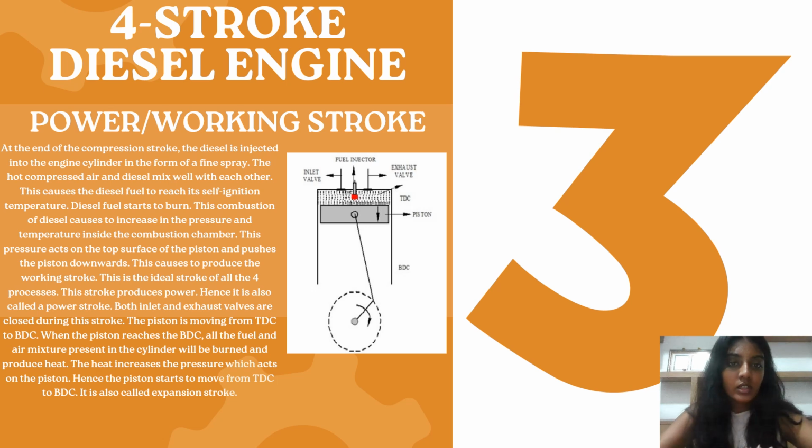Next, we have the power or working stroke. At the end of the compression stroke, the diesel is injected into the engine cylinder in the form of a fine spray. The hot compressed air and diesel mix well with each other. This causes the diesel fuel to reach its self-ignition temperature. The diesel fuel starts to burn, and the combustion of diesel leads to the increase in the pressure and temperature inside the combustion chamber. This pressure acts on the top surface of the piston and pushes the piston downwards, and this causes to produce the working stroke.